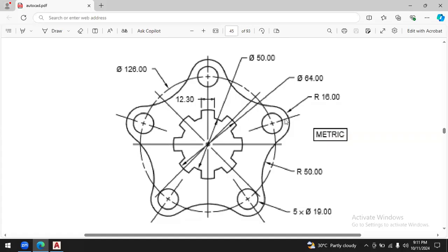In that case, I always suggest that you begin with the model in such a way that you cover, by manual drawing or modeling, only the first quadrant. Whatever is present in the first quadrant, just go for it and then apply the array command for the rest of the 3 quadrants.